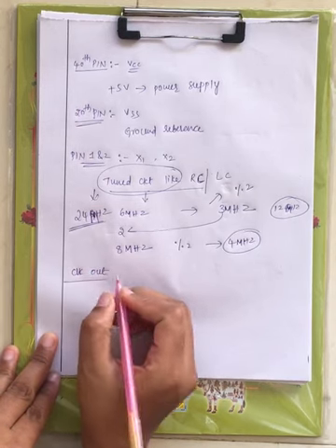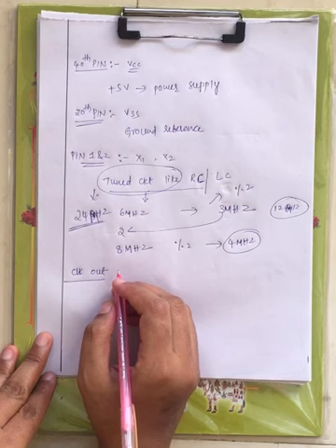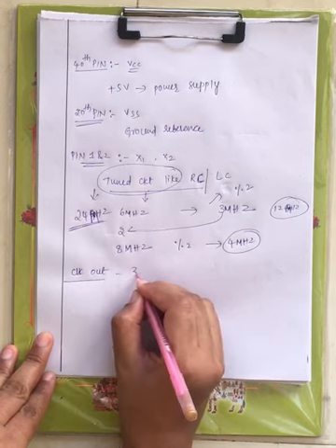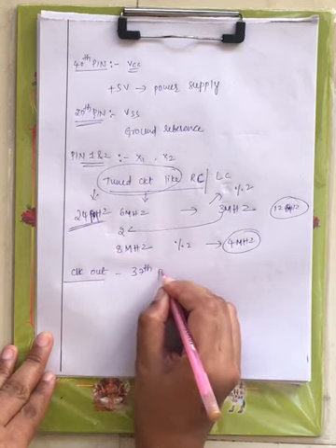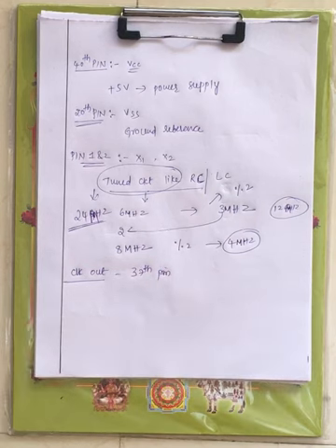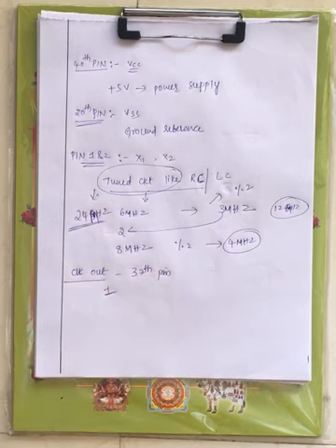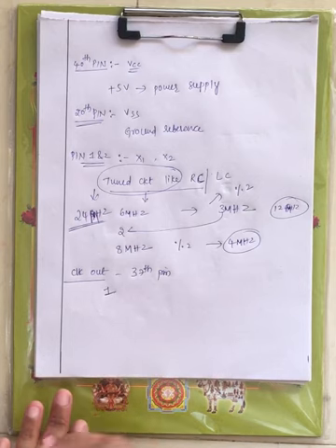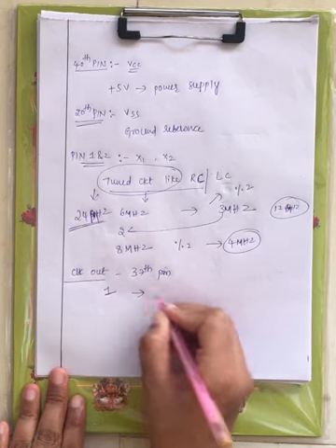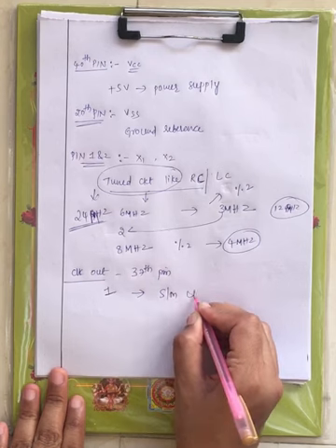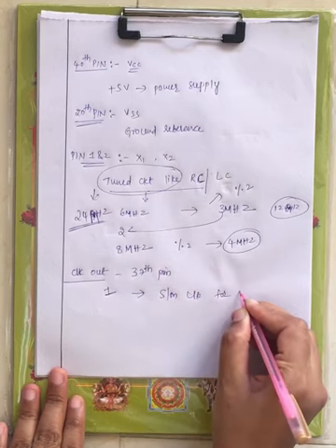Next we have the clock out signal, and this is provided at the 37th pin. As I have said, this is the signal used as a system clock for the other devices. When it is active high, that indicates 1, which means this signal is used as a system clock for other devices.